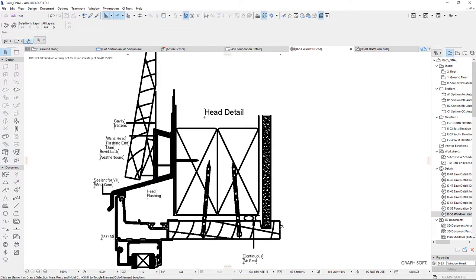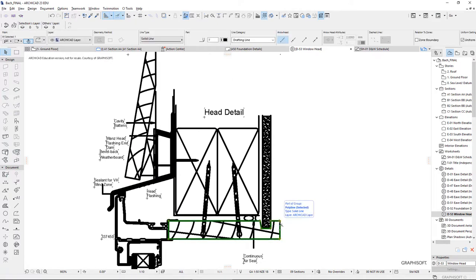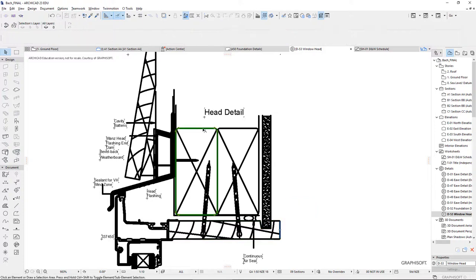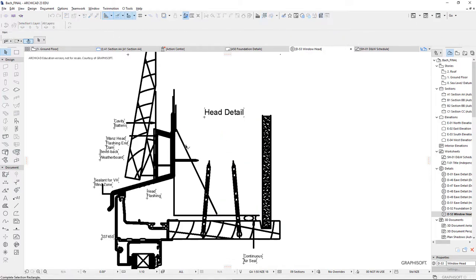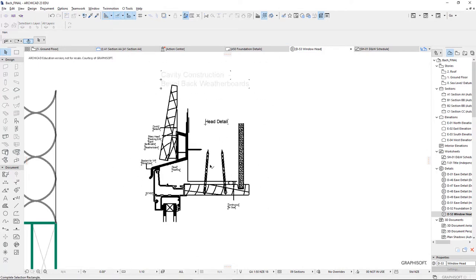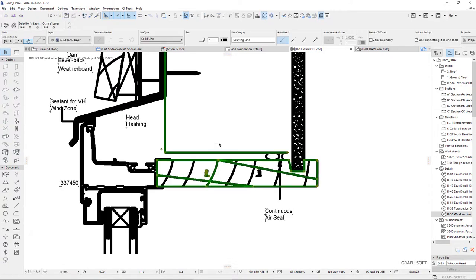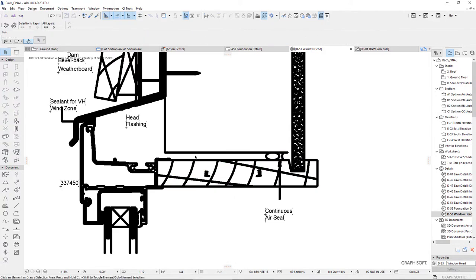So you're missing information here. You're missing whether this has got the right kind of jam liner, whether it's got the right kind of timber here. Do we need to get rid of those and put some of my other timber in? The insulation's missing. Is your building wrap there? Is your air seal there? I often get rid of these things like the nails because I don't want to see the nails. You have to tell someone that they're going to put those in place. And I need to go back to that mode, I think.